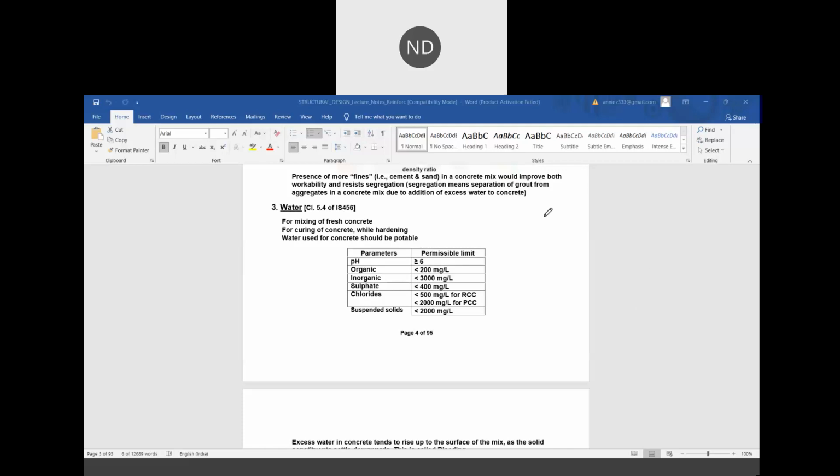The initial setting time of the test block made by this should not be less than 30 minutes and shall not differ by plus minus 30 minutes from the initial setting time. Previously, we had talked about this test of cements in the fourth semester.